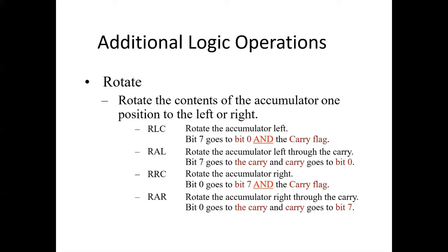It is also used to introduce a new bit value to the LS bit position. Put this bit value in the carry flag and then execute this instruction. For example, before the execution of this instruction, accumulator has the value 24H and carry flag has the value 0. So after executing RAL, accumulator will have the value 48H and carry flag will have the value 0.